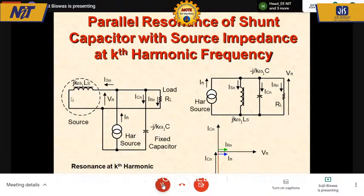And on the source side, because it is the kth harmonic, the reactance is k times larger, but the fundamental source is not going to be in my circuit anymore, because it's not going to be interactive with the nth harmonic. It's not drawing any power at the nth harmonic. It's not supplying any power. So I don't need to put my fundamental supply voltage there. I will replace it by a short circuit there and go ahead with my kth harmonic equivalent circuit.